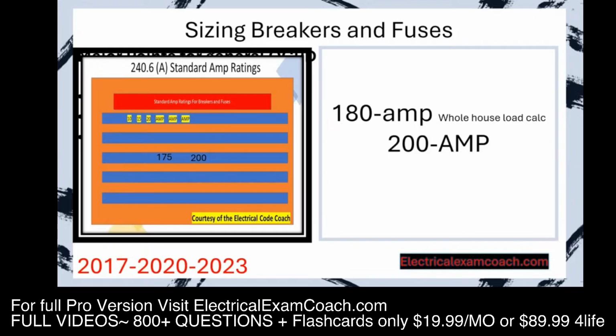But the question is what size is the service? Is it based off like the rating of the equipment bus? Maybe it's a 225 rated. No, it's actually based off the size of the main breaker or main fuse for that structure. So this would in fact be a 200 amp service. The load calculation dictated what size breaker we used, and the breaker size that we used dictated the size of the service.